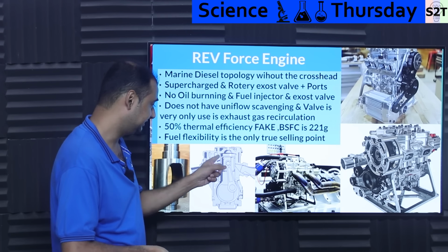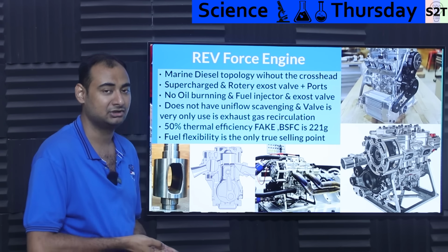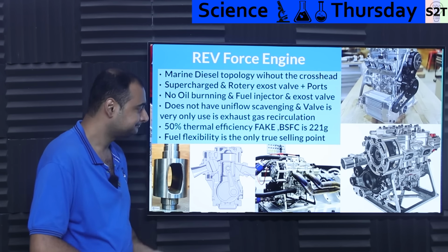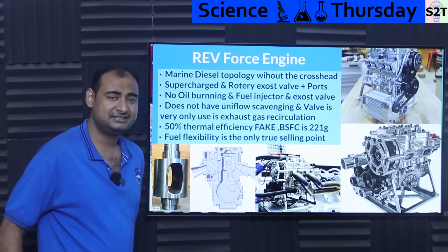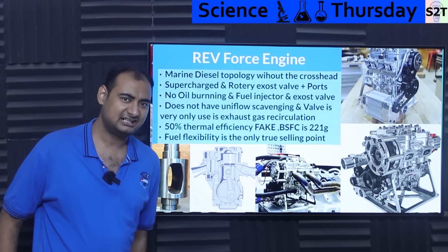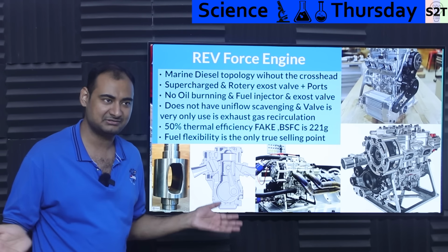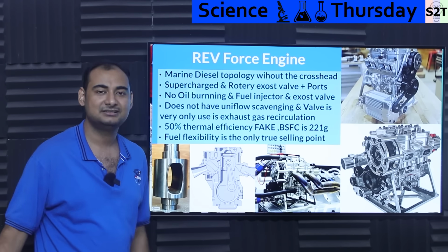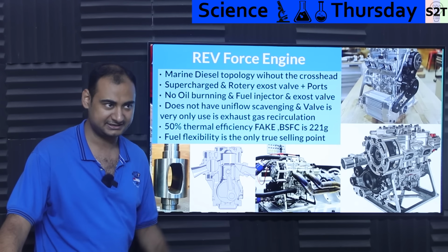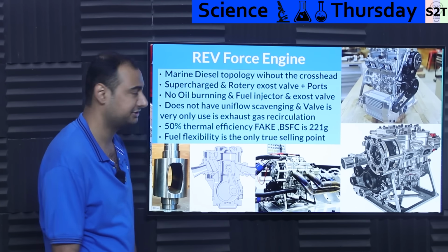In this, they are doing it by having multiple ports for hydrogen and all that jazz. So that's the only benefit, which again is not really that big of a benefit, because most engines are compatible with any fuel as long as you can change the fueling infrastructure. As in, a gas injector would be different than a liquid injector.